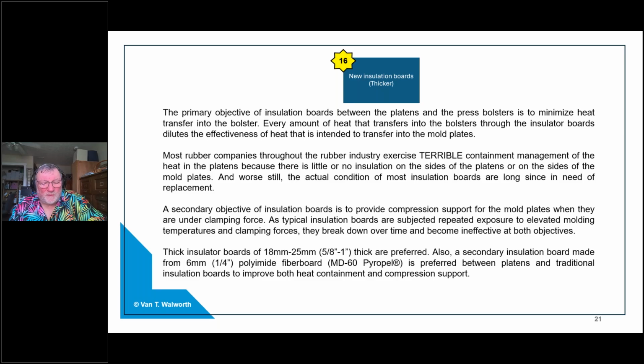It's a word about materials. Very likely none of you woke up this morning wondering, how can I use thermal diffusivity in a sentence? But all it means is how fast heat travels through something. We understand that travel of heat through aluminum and through copper is very, very fast, faster than heat passing through steel. But passing through the insulation materials, it's passing through very slowly.